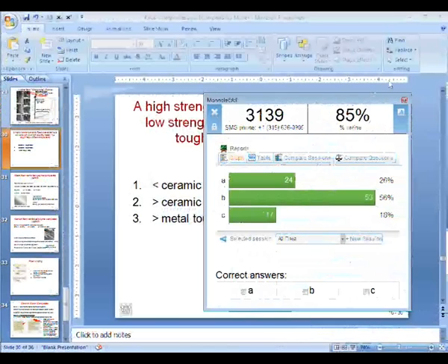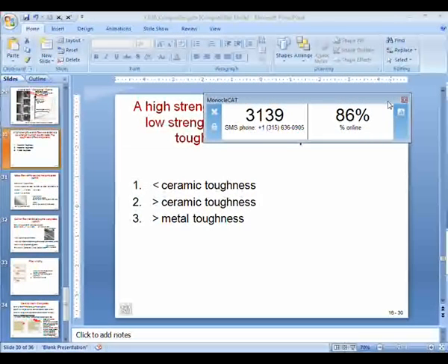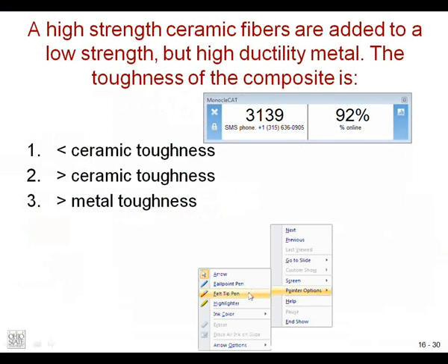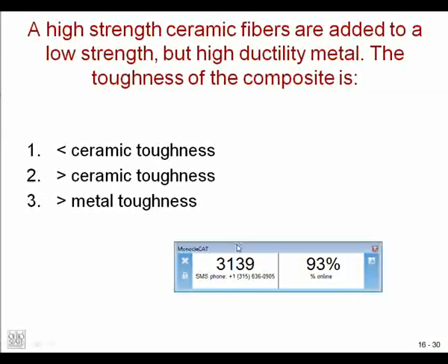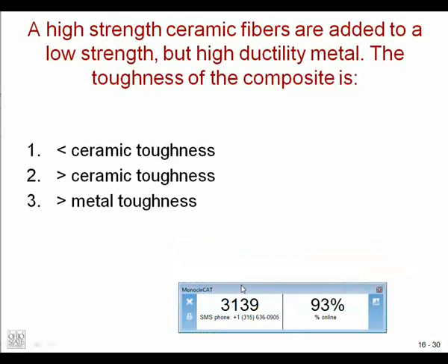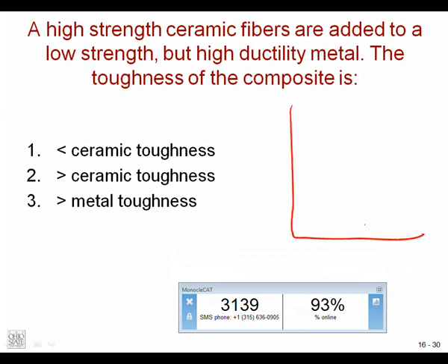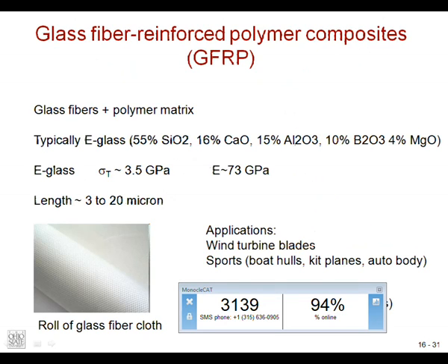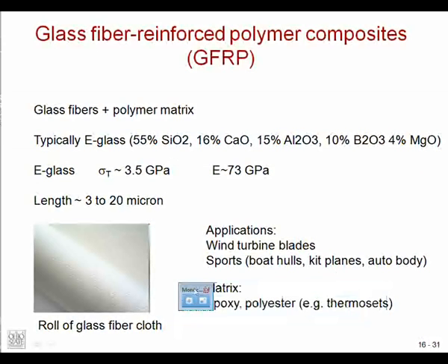Okay, good. So again, toughness is what? It's the area under that stress strain curve. So when we looked back at that, if there's the ceramic, there's the metal, our composite's somewhere in here, so we're still not as tough as the metal. There's still less area under that stress strain curve. So even the toughness is somewhere in between, because the other two properties are in between.